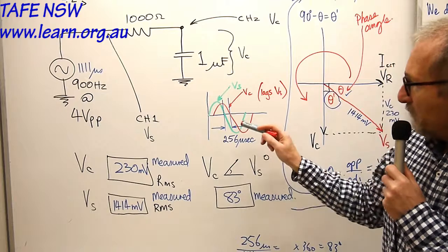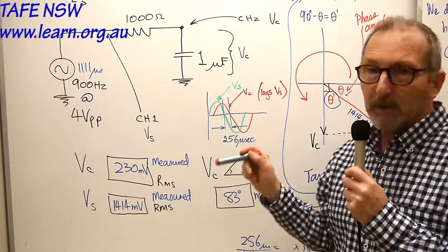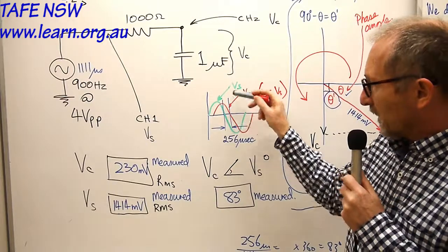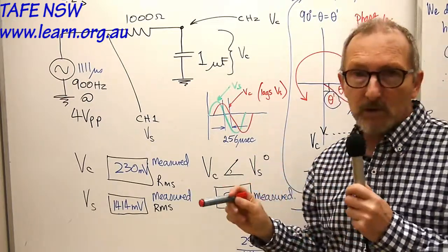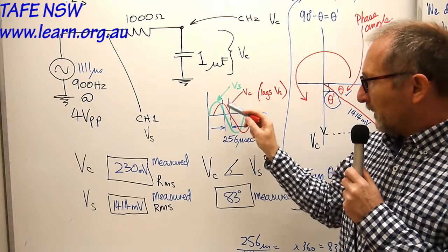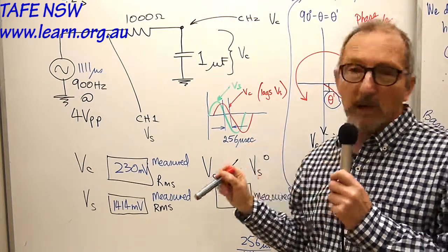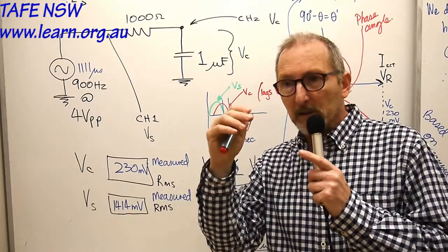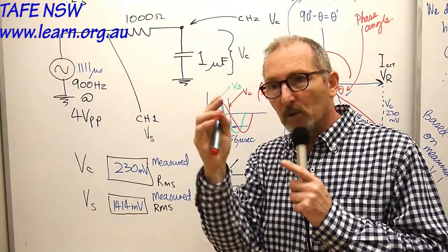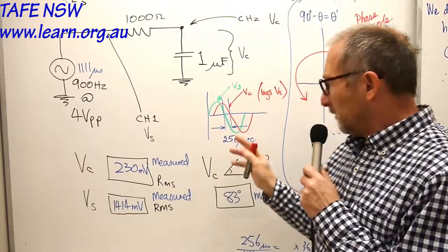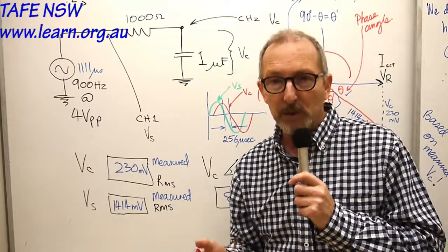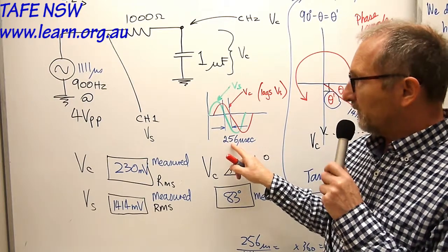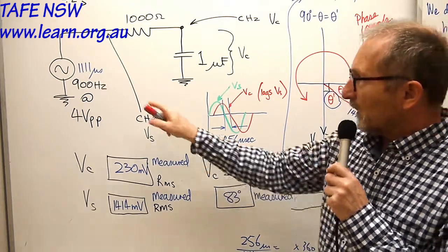And then we measured the time difference between the two waveforms using the oscilloscope, and we used the cursors. Students did a good job with that overall. When I checked their results, I measured 256 microseconds. I probably could have blown the waveforms up a little bit more and spread them out, but 256 seemed to be a pretty good result. I was able to use that 256 microseconds with the